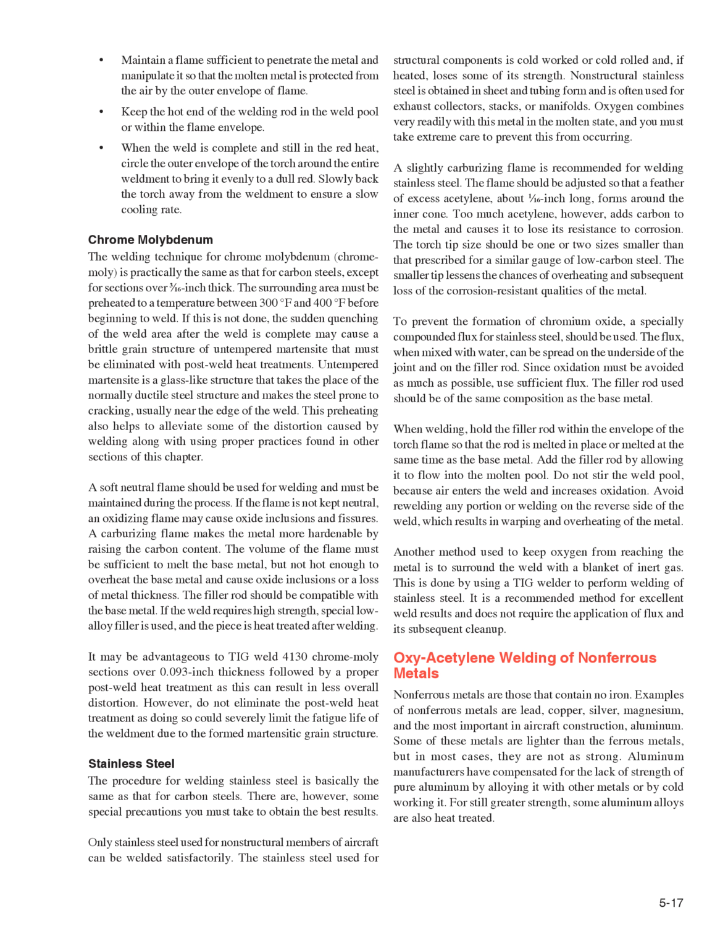Chrome molybdenum. The welding technique for chrome molybdenum, chrome moly, is practically the same as that for carbon steels, except for sections over 3/16 inch thick. The surrounding area must be preheated to a temperature between 300 degrees Fahrenheit and 400 degrees Fahrenheit before beginning to weld.